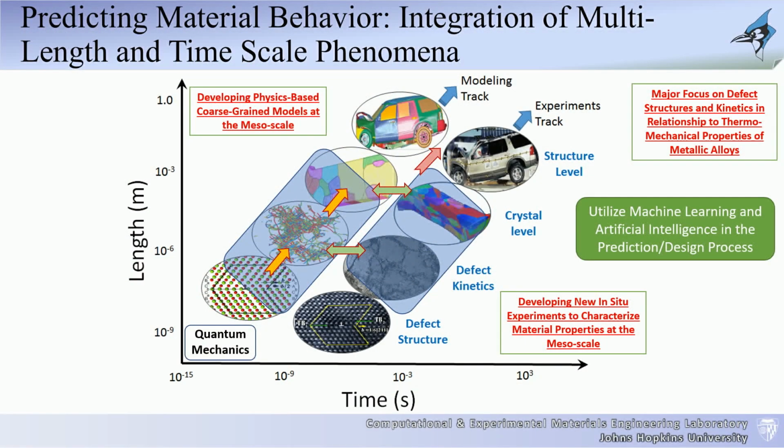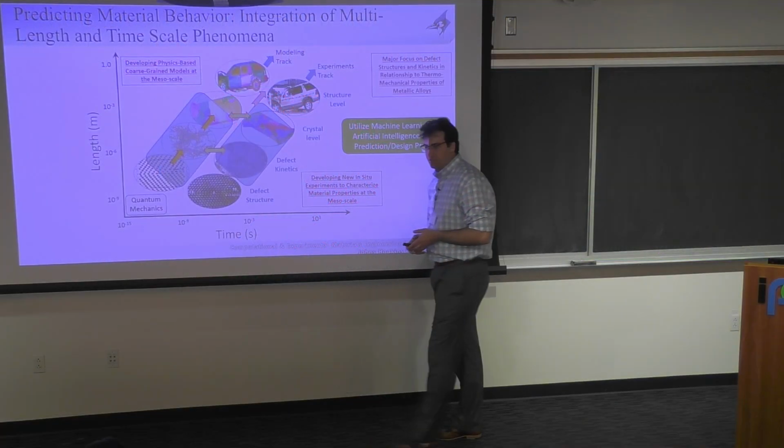So there are a lot of people that work on this level that try to develop homogenization techniques as well as some type of approximations where they can extract information from the crystal level if they have tens of grains, because again, they have an issue with numbers: the larger the simulation volume they have, the number of equations that they're trying to solve becomes huge. They're not able to get to a component level structure, but you can inform the FEM simulations a lot with these types of crystal plasticity analyses.